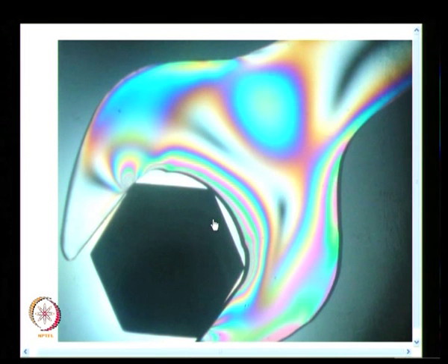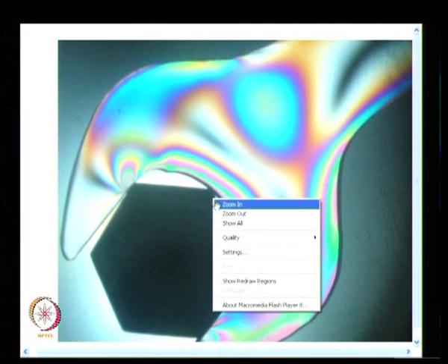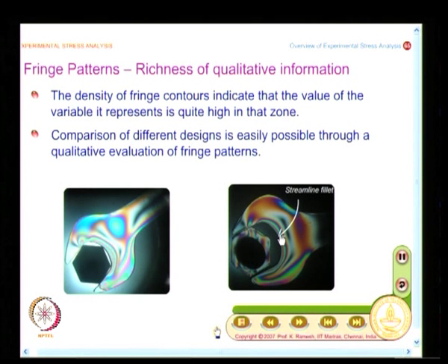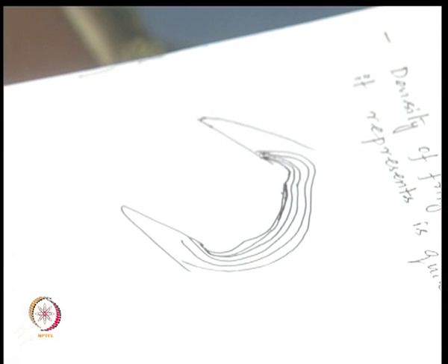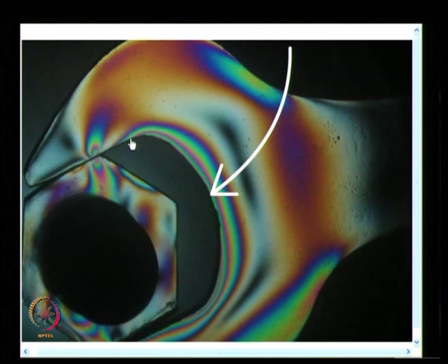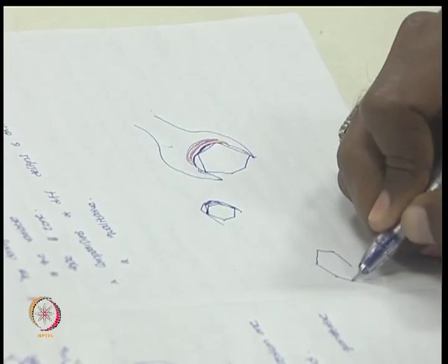Now, I will go and show the other one, then come back to this, so that you will know what the difference is. I take this example, and what I find here is that the contour is smooth, the fillet is non-circular, and these fringes are more or less tangential to the boundary; they merge with the boundary. These are called streamline fillets. Only when you see the difference will you know what the advantage is, and they are very strong.